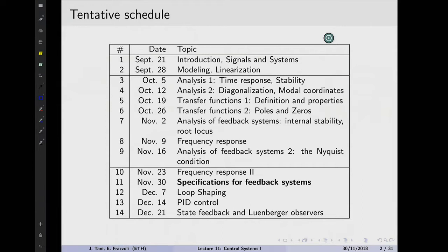And we looked into Bode plots, into Nyquist plots, and into the root locus as the different methods to assess what were the conditions, and particularly the stability of the closed loop system in a negative feedback loop by only doing considerations based on the open loop transfer function.